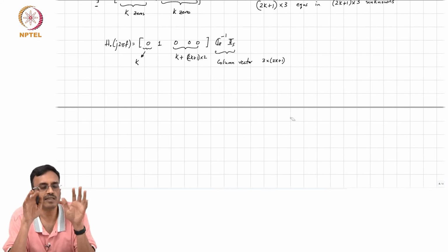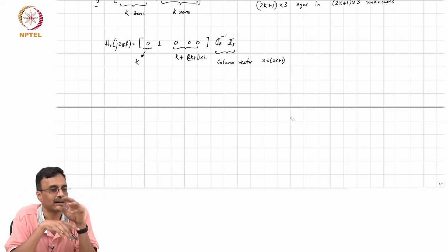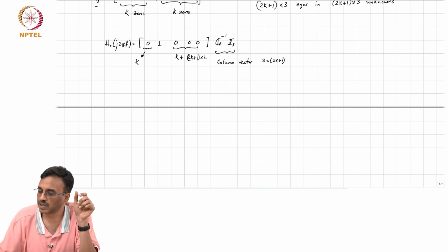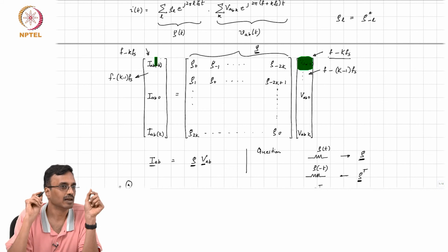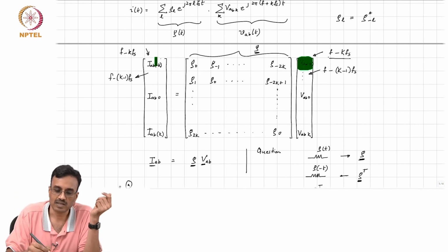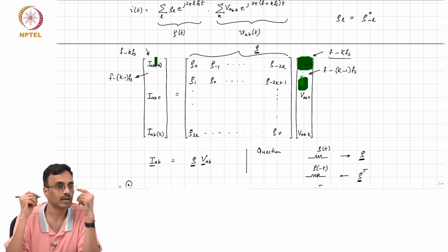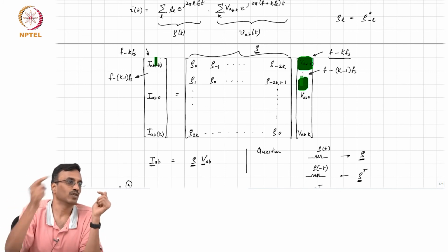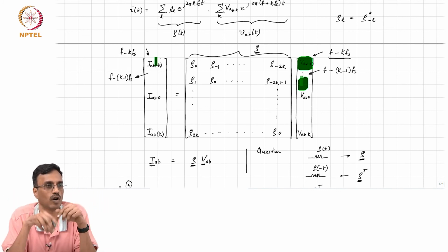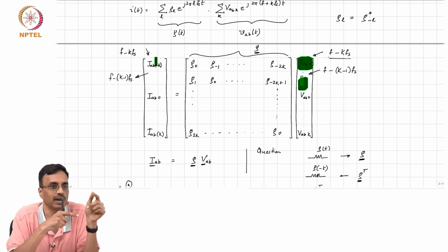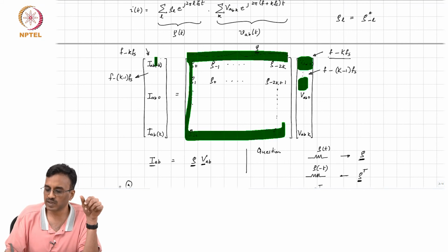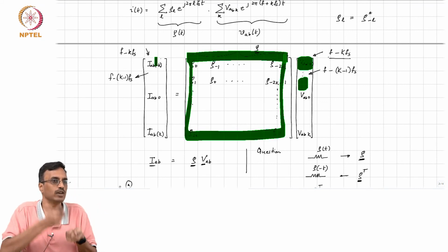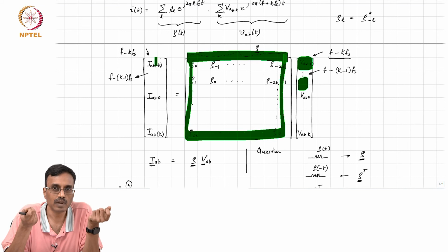What this time variance is doing is that, because this conductance is changing with time, the fact that the conductance matrix, this small g, is not diagonal means that stuff at one frequency can jump up or down, or do both, or remain at the same frequency, depending on this matrix, which is equivalent to saying, depending on the way you change that resistance with time, right?